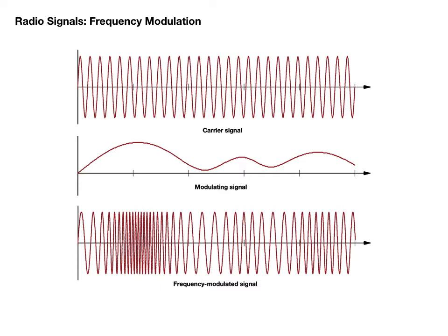For example, if you and a friend were talking on 146.52 MHz, the carrier frequency would be 146.52 MHz, and this is the frequency that you would set your radio to. The modulating signals are your voices. Over the course of a transmission, the actual output frequency will vary above and below the carrier frequency. How much the signal varies is called the bandwidth. The FM signals that we use in amateur radio have a bandwidth between 10 kHz and 15 kHz.